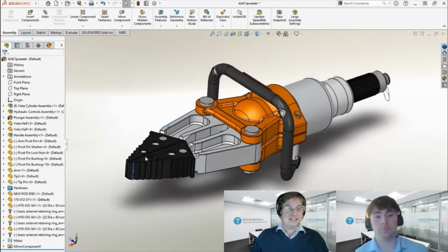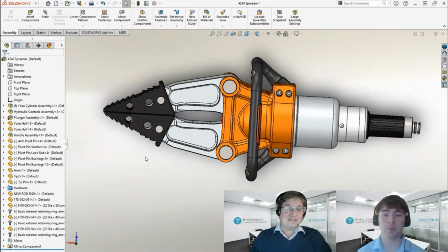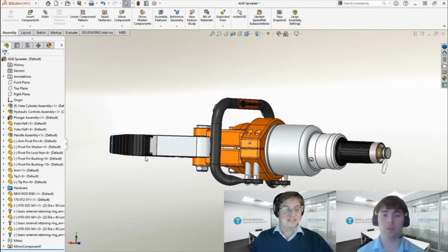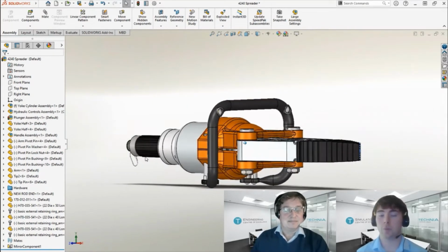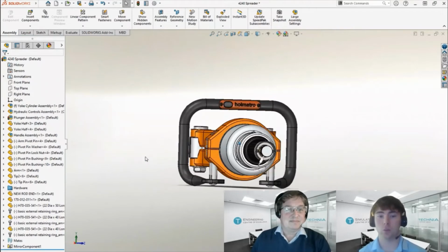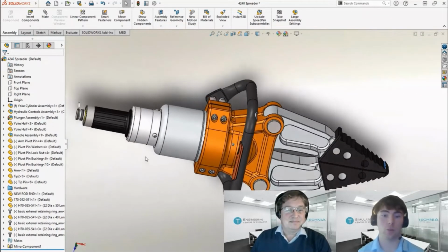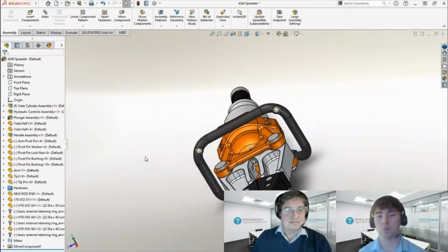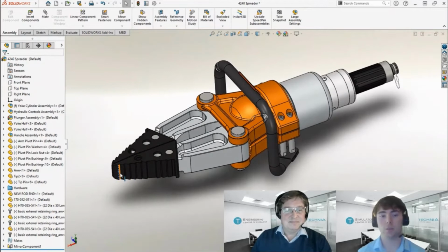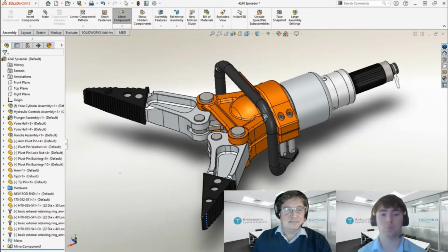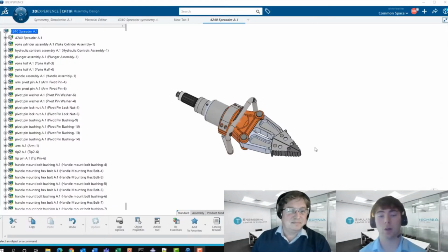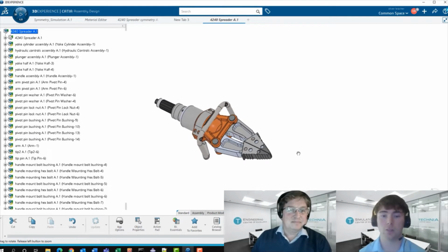Okay, great. Well, in simulation, those questions are called load cases. Depending on the simulation, it might be the case that we only need to consider one of the parts in the assembly to get an accurate representation. Or it might be that we can model multiple parts in order to get the right behavior on that one part of interest. Reducing the number of parts will reduce the runtime of the model, but it can affect accuracy. So it's up to the engineer to decide when it's appropriate to make these assumptions and approximations, but I can help you with that. So why don't we go through your load cases now?